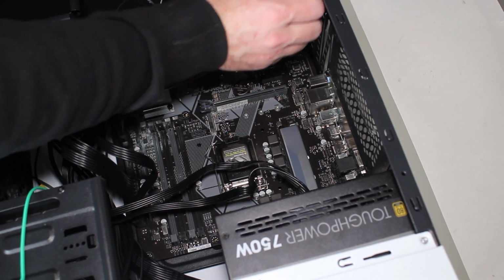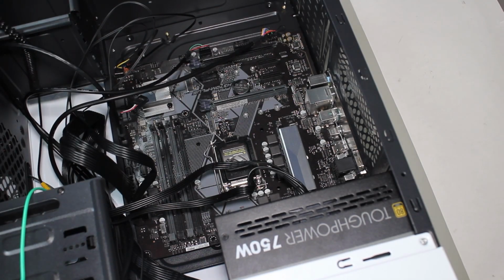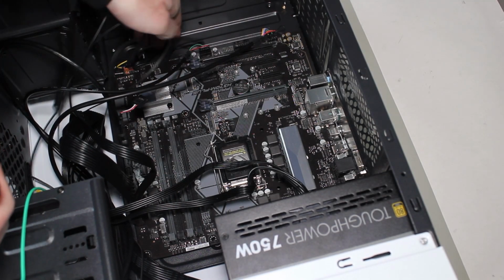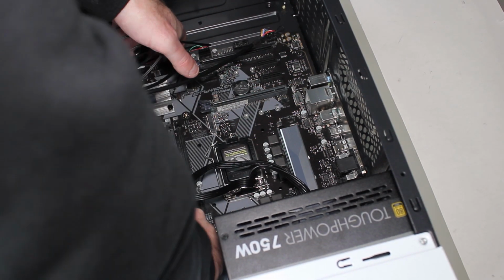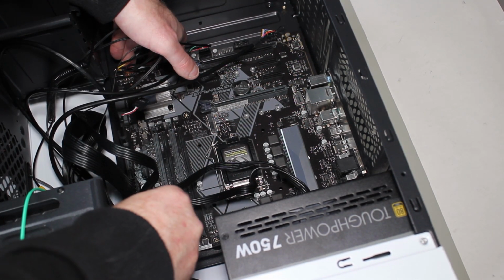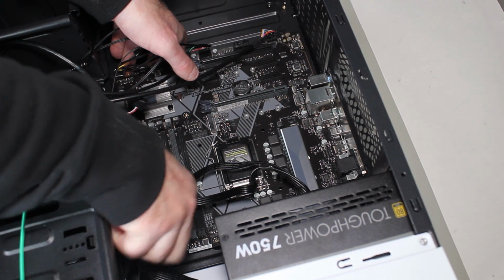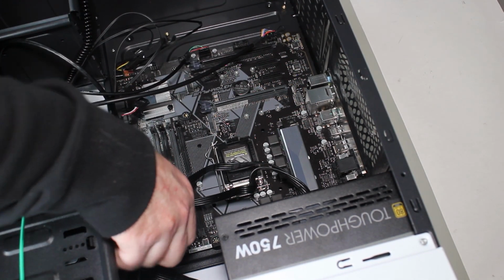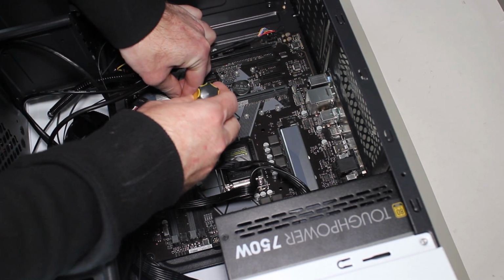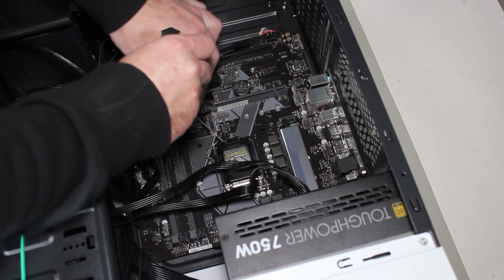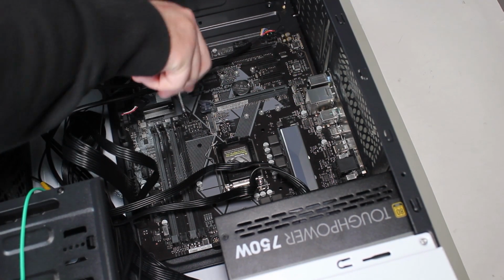The last step is to screw the motherboard into place. I'll start by screwing in a corner screw. Once this screw is in place, I will adjust the motherboard so the other screw holes are in line with the standoffs. Once done, I will screw in the opposite corner screw of the motherboard. Screwing the opposite corner screws in first helps prevent the motherboard from being installed misaligned. I will next screw in the other 2 corner screws. Once this is done, I will screw in the last remaining 4 screws for a total of 8.